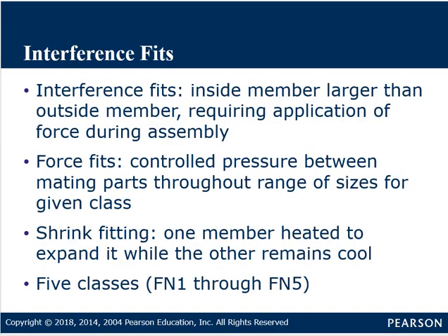Now interference fits are different. In an interference fit, the shaft is always bigger than the hole, and you want to put these parts together such that they stay together. There are different classes of interference fits. One is called a force fit, where you're controlling the pressure between the mating parts throughout the size range. That means you're forcing these parts to go together.